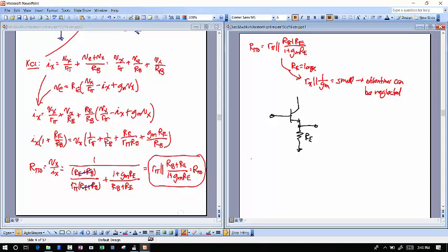where that C pi is, if you had to tell me what the gain was across this, VI to V out, what is that gain? No, 0.7 is the DC voltage drop across it. What's the gain? Small signal gain. Signal here to signal there. Basically a voltage divider, you see. Right? It's kind of like that.